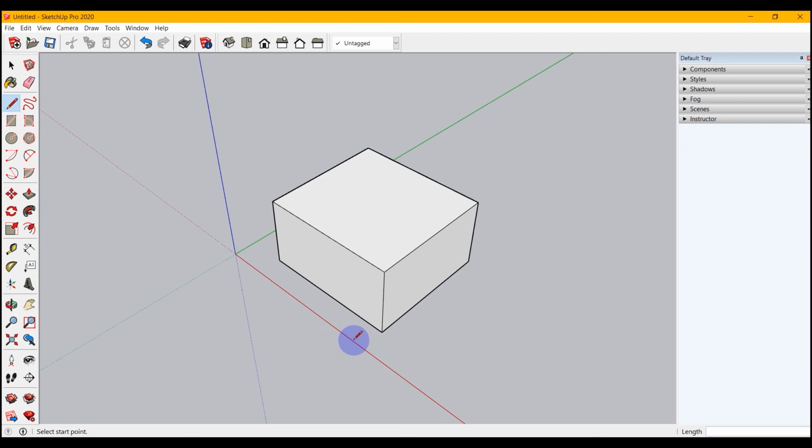Now this line tool can also be used to draw onto this object. One of the nice things about this tool is that once we have faces in the scene, we can start drawing on these faces. So if I want, I can snap my line tool to a corner, to the edge, or right here to a midpoint, which shows up in cyan. If I snap to the midpoint and drag along the red axis, I have cut the top in half. Then I can use that as the basis to draw another shape. So now I am just drawing on my existing object.